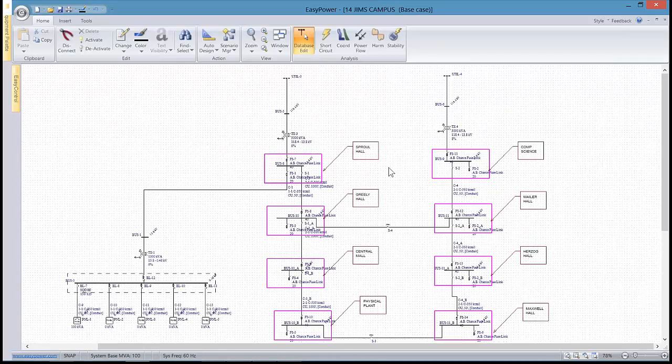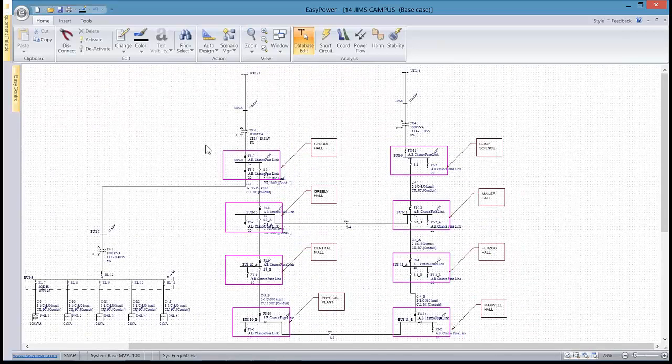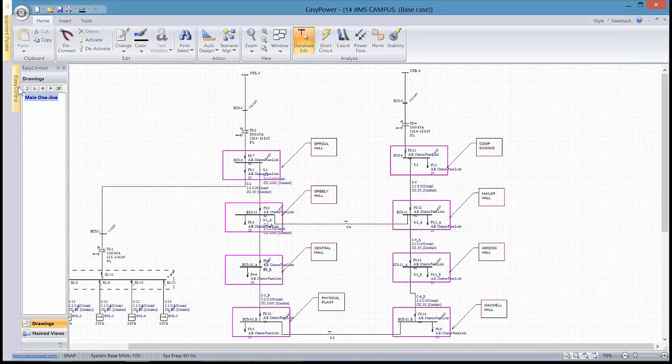Now, what I'm referring to in terms of easy controls is that by putting this at my high level or at the top of the one-line diagram, I can also set up a named view. So as we come back to this, I'm going to call this my ring HV. By just clicking on this named view, it will bring me back to this zoom and pan settings so that I can come back to it as we have more complicated designs.